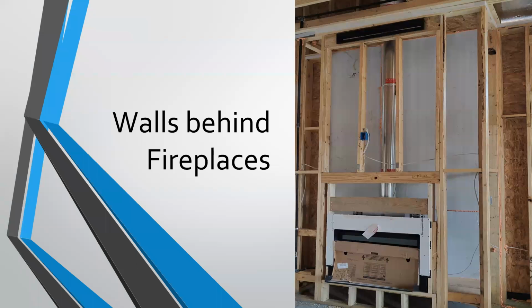So the builder correctly identified this thermal envelope here. This is what I see a lot of times: they don't think this through. It's not on the plans this way. All they were really doing is building the exterior wall. They're building a fireplace in front of it. And then someone is determining where the air barrier and insulation boundary is to create the thermal envelope.